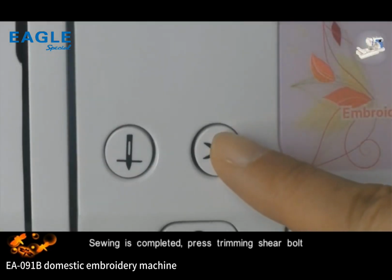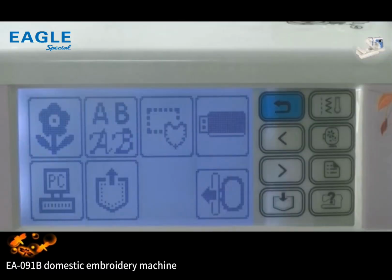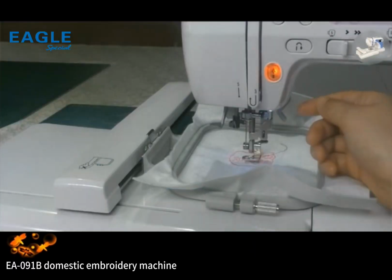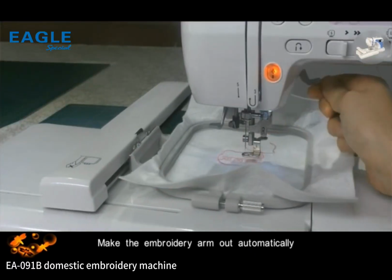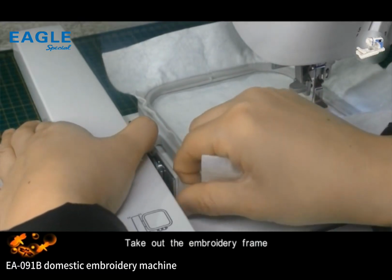Sewing is completed. Press the thread trimming shear button. After the completion, press the dotted box out key and lift the presser foot. Make the embroidery arm come out automatically. Take out the embroidery frame.